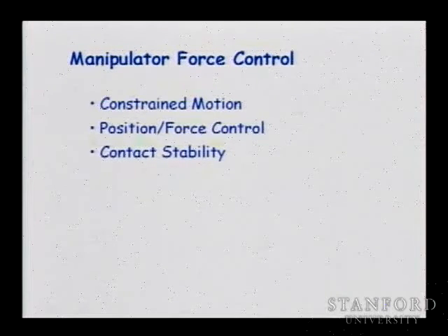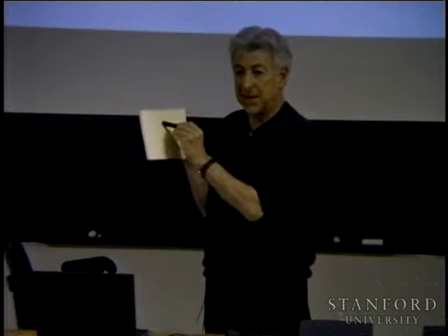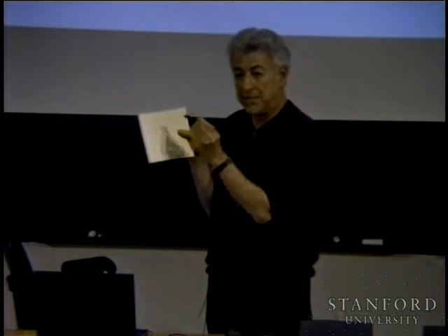Finally, we need to deal with the problem of controlling contact. So when you are moving in space is one thing, but when we are going to move in contact space, it's a different thing. Applying this force puts the whole structure under a constraint, and you have to account for these constraints and compute the normals, so as to find the reaction forces in order to control the forces being applied to the environment.